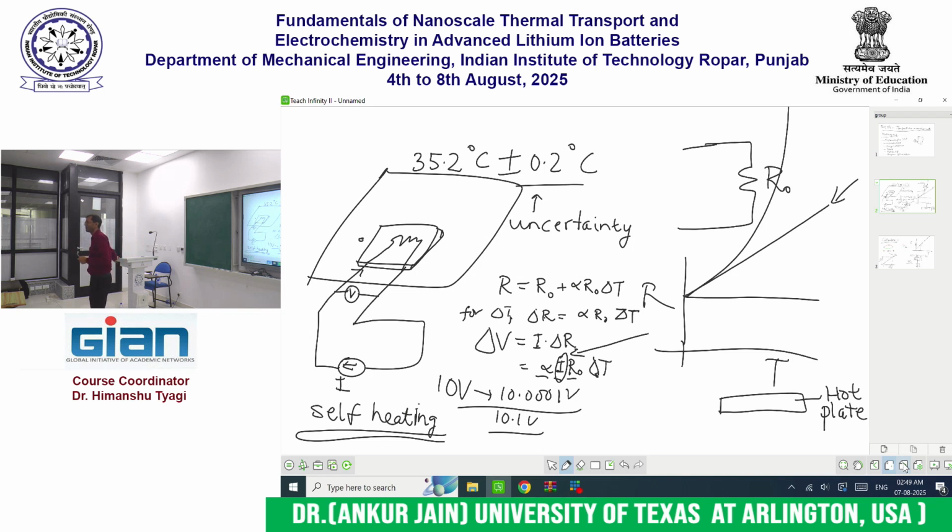In your presentations, if you show the calibration plot and if those points are very closely spaced, done. People will never question anything else that is going on in your measurements. If on the other hand you just show the temperature measurement, and especially if you say that my temperature was measured to be 26.329 degrees Celsius, that is what sets up a lot of alarm bells.